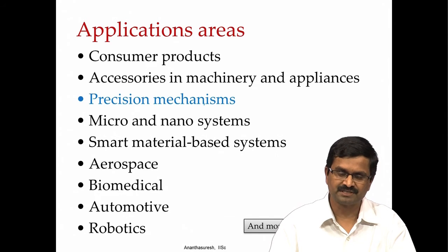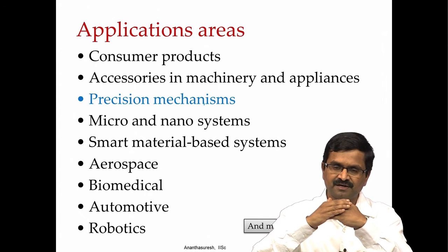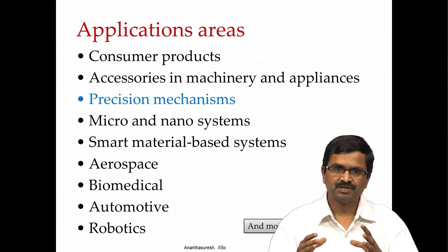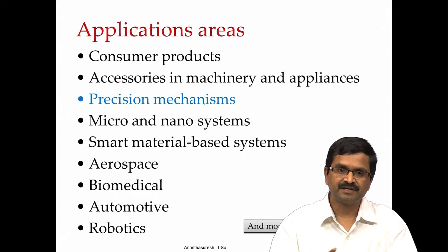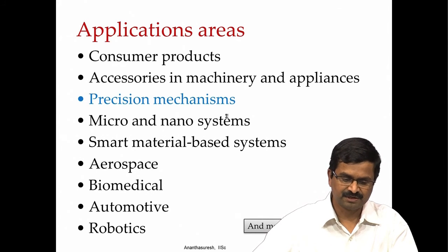That happens only when you have joints and there are two surfaces which have to contact for the motion to ensue. When you use a fully compliant mechanism, meaning the one that does not have any kinematic joints or kinematic pairs at all, then it is void of the problem due to friction and backlash. So, people have been using it in precision mechanisms.